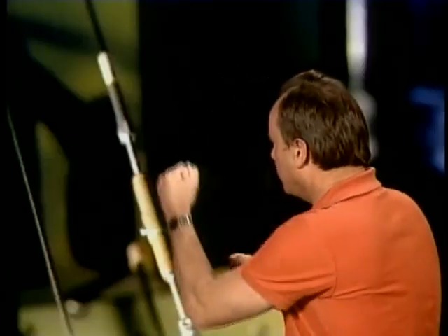So if you have a push-pull type system rather than a cable type system, you check for proper thread engagement at the ends by using the inspection holes provided in the airplane for doing that.